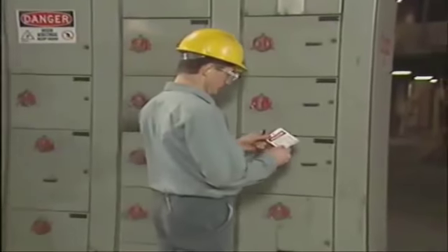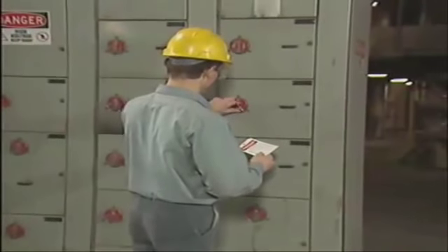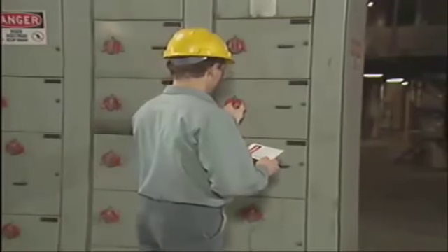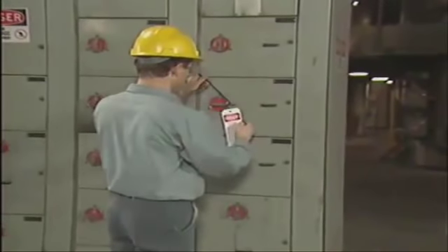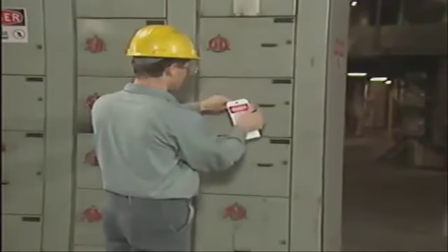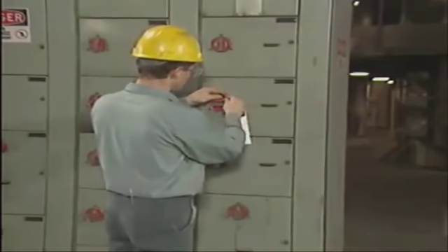In this part, we'll look at general procedures for troubleshooting a DC motor, and we'll see how to test for grounds, opens, and shorts. The motor to be checked should be de-energized, locked out, and tagged according to approved procedures. Troubleshooting a de-energized motor helps prevent personal injury and protects the motor and the test equipment from damage.